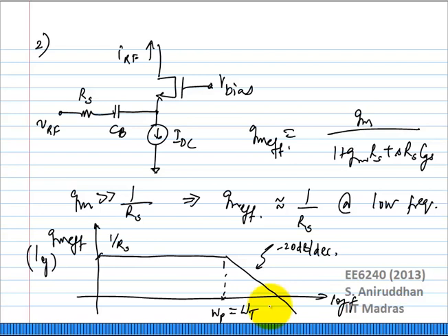So this is obviously a very wideband transconductor. What is the problem with this again? Does it take up any headroom here? It doesn't because you are AC coupling it through a capacitor. You don't care about the headroom. Does it add noise? Of course it does add noise. Any other issues? Of course, it will load the LNA, right? So those issues are still there.